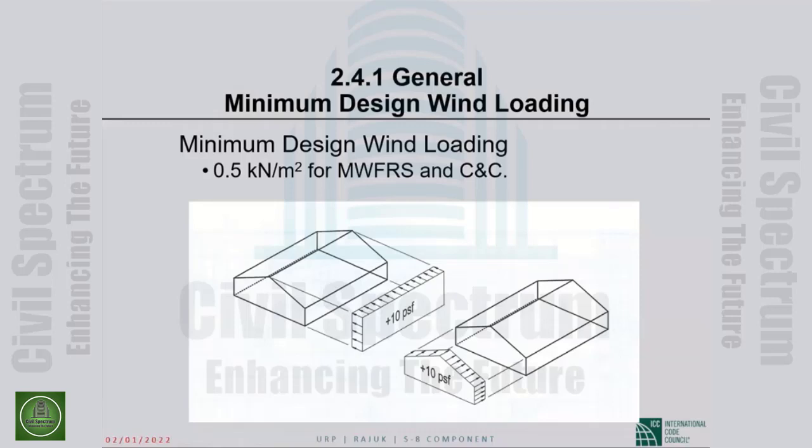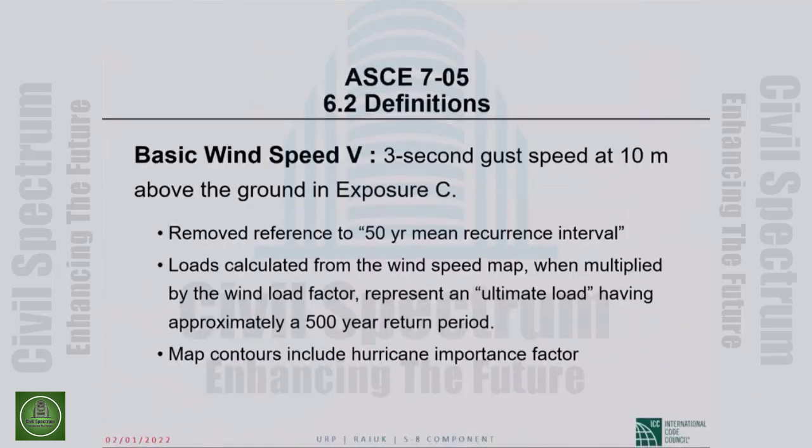Now, the idea here is, we have a pressure distribution that we have calculated. We are not saying if you calculate values less than 10 pounds per square foot, make it equal to 10 pounds per square foot. No, you don't tamper with what you have calculated. You design your building for that distribution and also this distribution. This is like an additional load case. What I just said is quite important. But these minimum design wind loads, there are times when they govern.